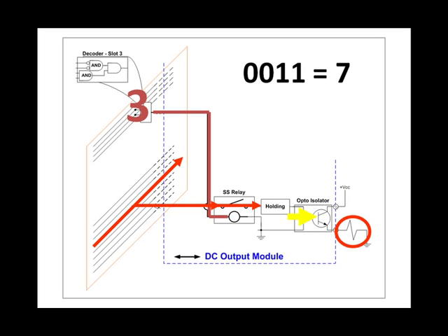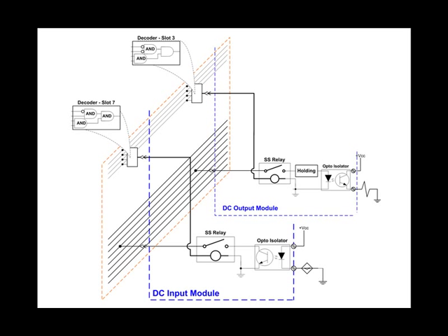There are, however, a few points that I would like to add to this. Only 8 conductors are shown here for the data bus on the backplane to represent 16 that actually exist. There's actually quite a few more lines than 16. There's support lines for voltages, grounding, and other purposes. Only one 16-bit word of data can exist on the backplane at any given instant. Don't forget this. Only one 16-bit word of data can exist on the backplane at any given instant.